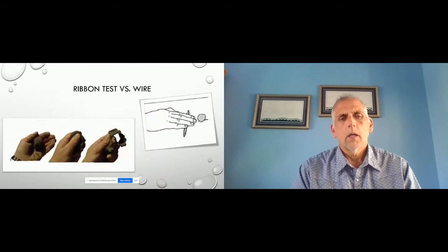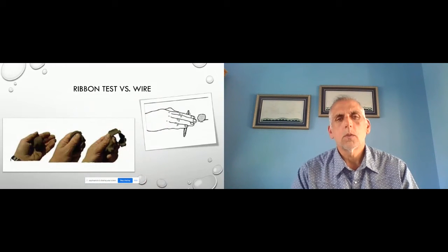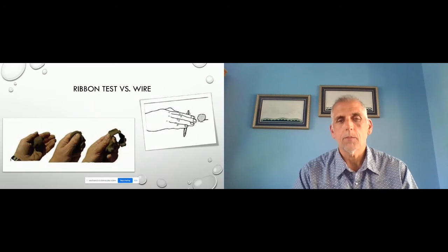When I started, when we were testing for mineralogy, which would tell us if the soil was expansive or slightly expansive, we did a ribbon. If the ribbon was 2 inches long, then it was slightly expansive. If it was 3 inches long, then it was expansive. That wasn't in the rule, but that was the way that we were taught to do it. In the rule, it talks about whether or not it's very firm, very sticky, and very plastic.